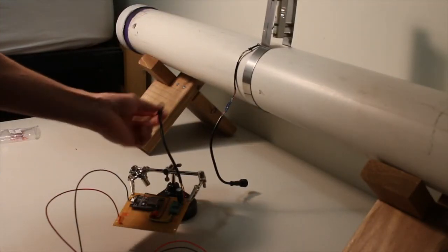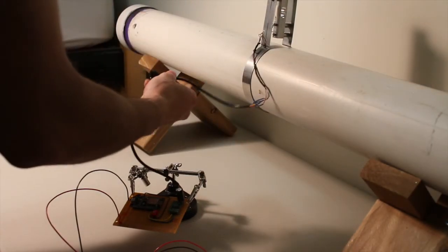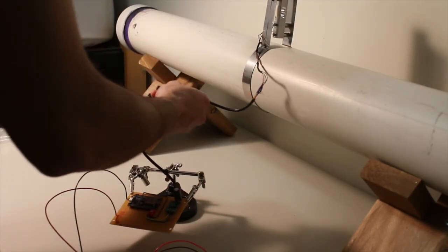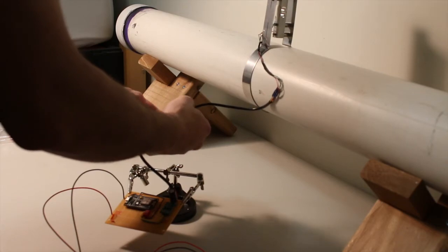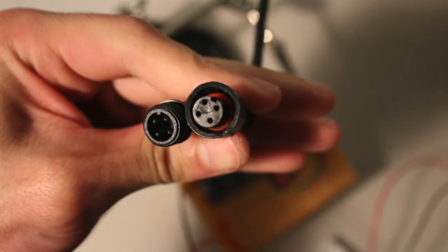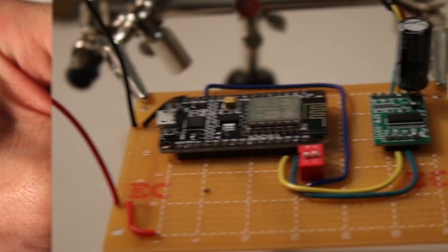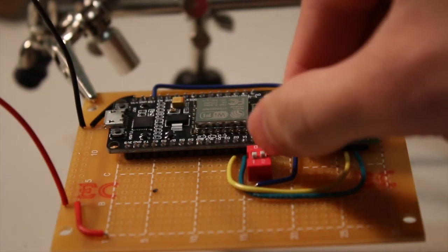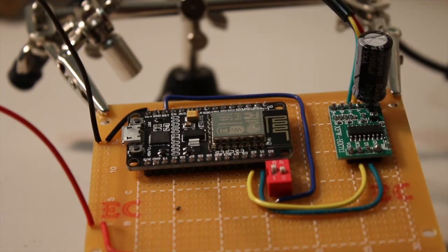Next, connect the 4-pin DIN cable from the load cell to the receptacle on the main circuit board. Once the male and female terminals are securely connected, screw on the waterproof cover. The keyed layout of this connector prevents technicians from incorrectly installing the load cell. Lastly, using the power button, turn on the circuit and use the dip switches to enable deep sleep mode on the module.